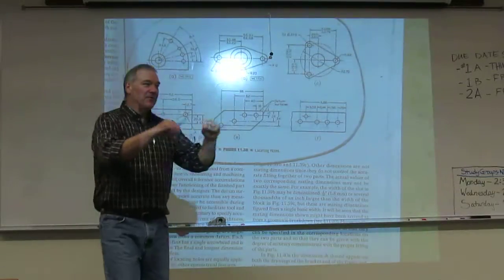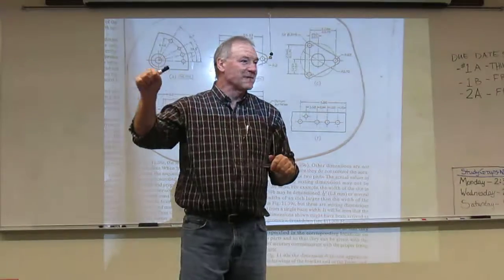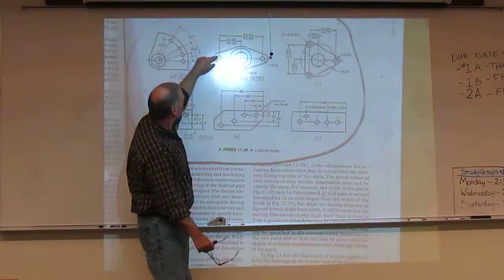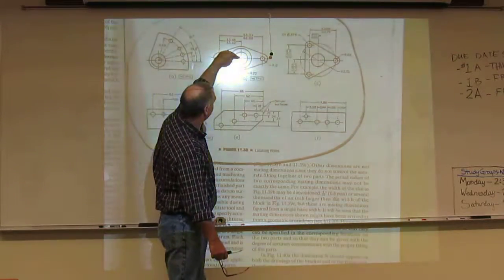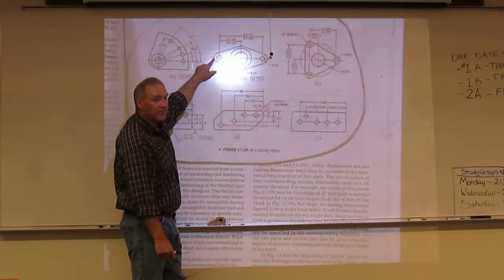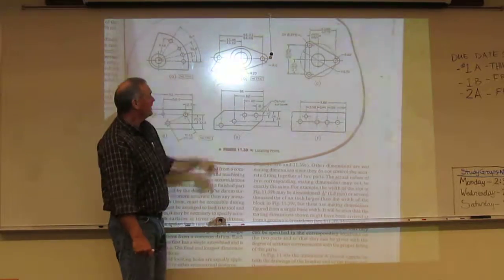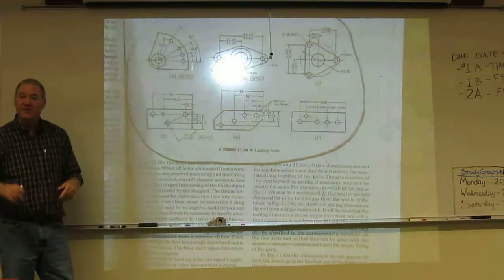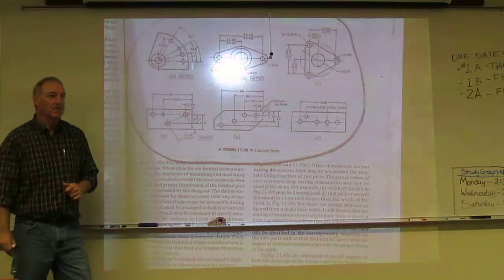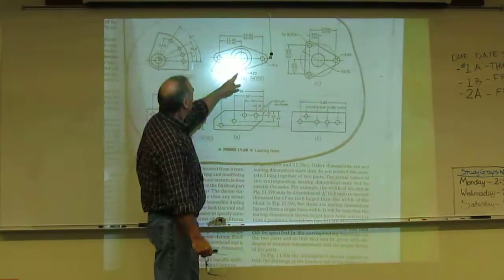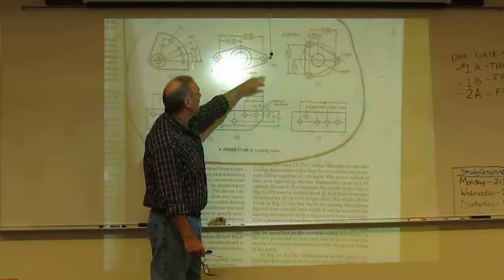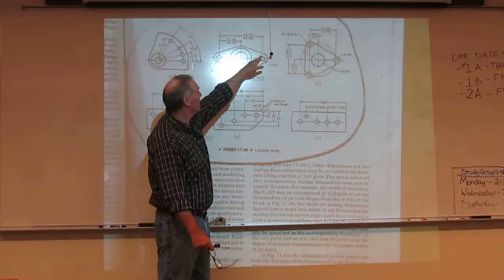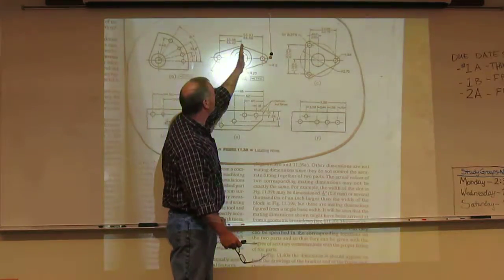We had a lot of questions. When do I extend these center lines to other holes? This is a great example right here. So they've got this center, it sits horizontally the same as that one and that one. They brought the center line all the way through. What does that do for you? It locates in that dimension, in this case that Y dimension, where all of them sit. So that's your location. Then they only needed width, that one and that one. And for some reason they thought, well, this one's more important. Once I have that, I'm going to come back to here instead of going from center here to center here.